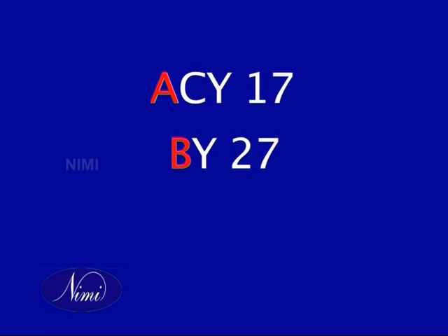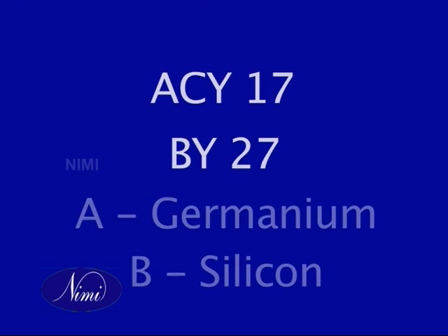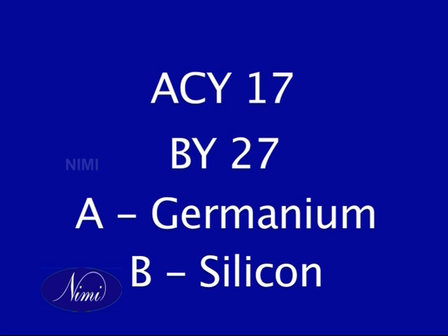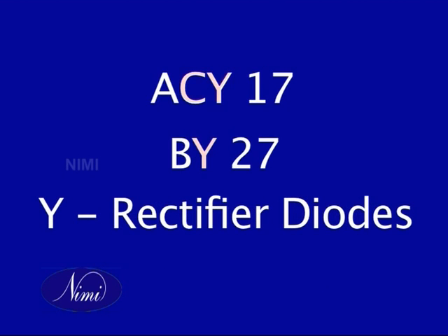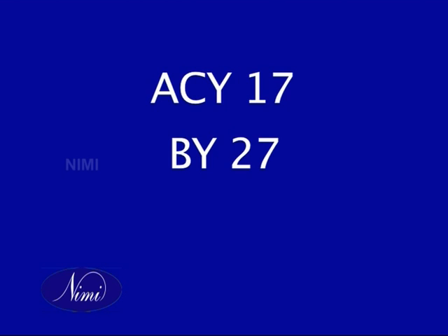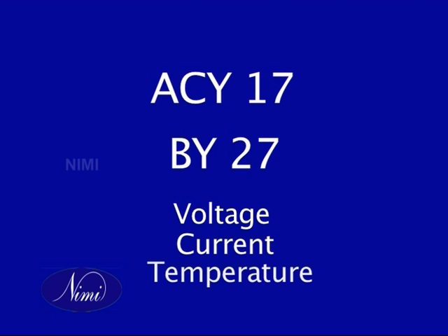The first letter in the Pro-Electron type code indicates the type of semiconductor material used in making the device. The second and third letters indicate the application of the component. The numeral after the second or third letter is the code number of its detailed voltage, current, and temperature specification.